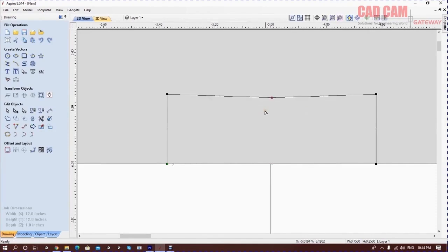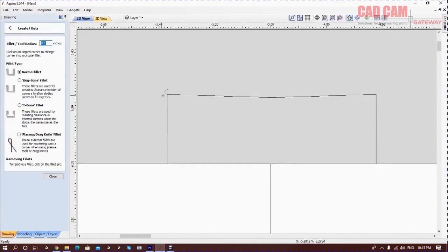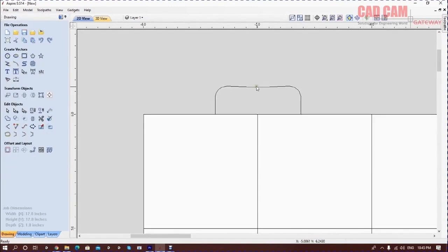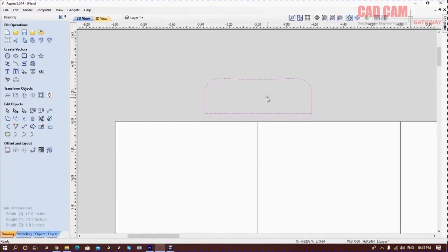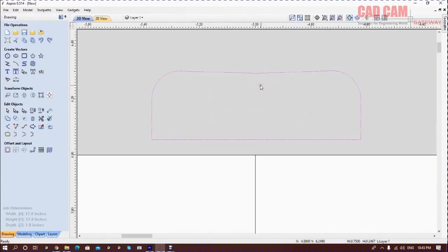After that, use the flare command. I use the flare command with 0.1 and add it around on this side as well as on that side. It's up to you. You can make it as big or as small as you like. This was a rectangle, so I moved it up a little. When I do it, the rectangle becomes a closed object, but we don't want a closed object. I had requested you earlier as well that the cross-section should be an open vector.